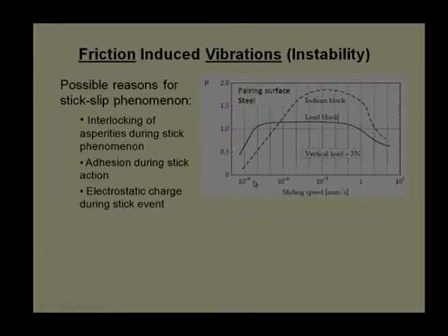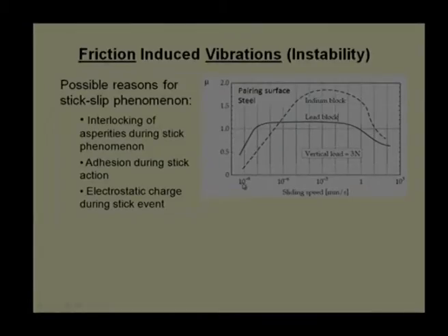It shows that when you are pushing one block on another block, even though the applied force is lesser than the static friction force, there will be some micro slip. That is why the speed is shown here in 10 to the minus 9 mm per second, which is very low, negligible. We cannot detect it by naked eye. In that case, the coefficient of friction is continuously increasing.